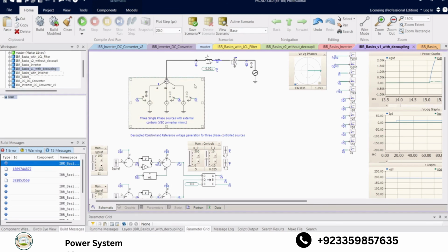So this is actually why I wanted to do this, because this is very simple to understand. There is no inverter, nothing, just a simple understanding of how IBR works. I mean how I can exchange power with the grid if I have a control source, just like in a synchronous machine. For example, in a synchronous machine I have a control source. I can control the voltage and the magnitude of that synchronous machine. So it's a similar case here, and we will be developing this slowly.